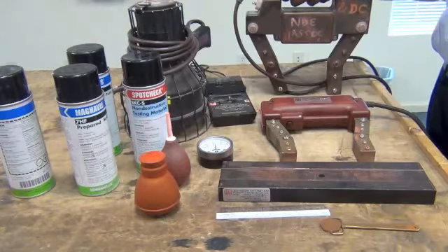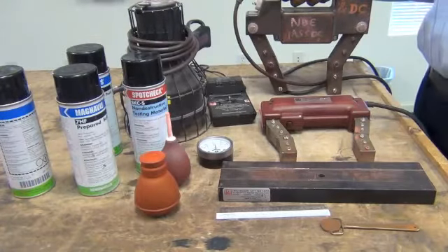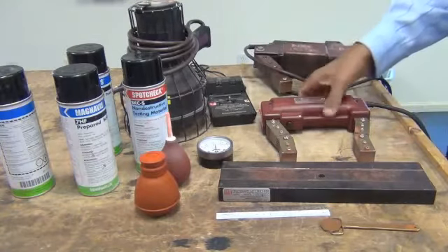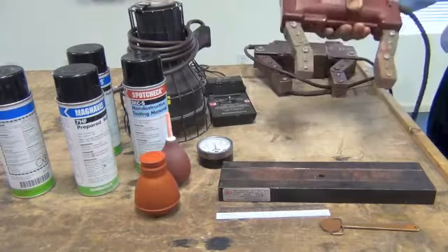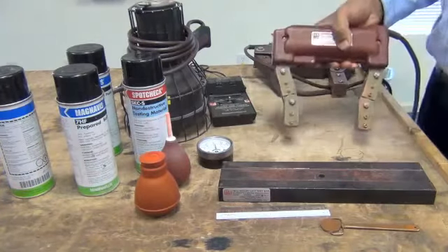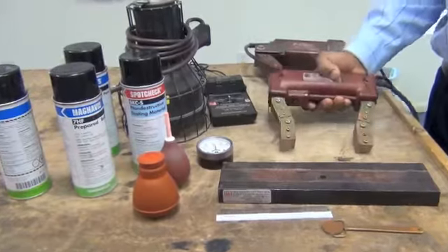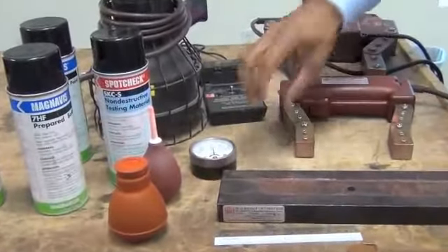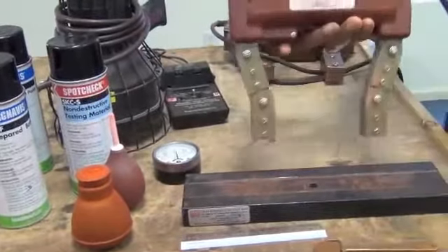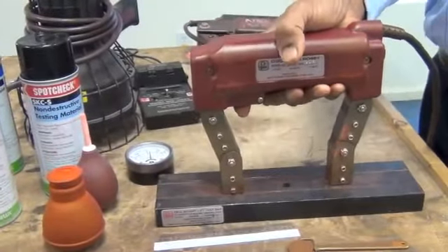The technician who is using the DC yoke really gets tired fast. So the preferred yoke for testing is the AC yoke. In some cases, the yoke can have an additional light right here to get some extra visible light. Here is the 10-pound weight. To check the yoke lifting capacity, we put the yoke here and then we lift it.